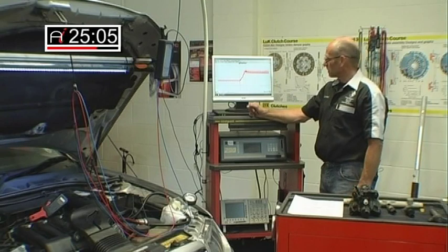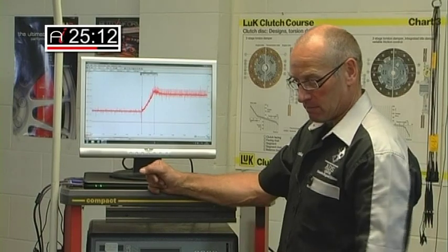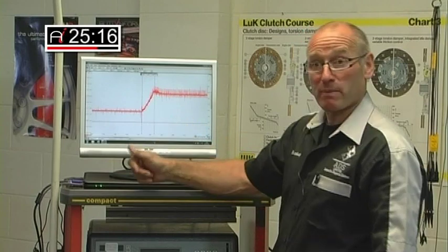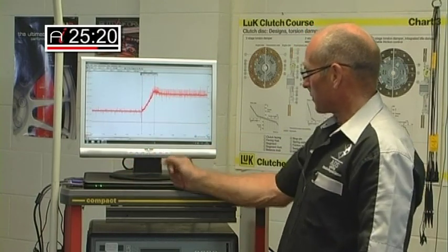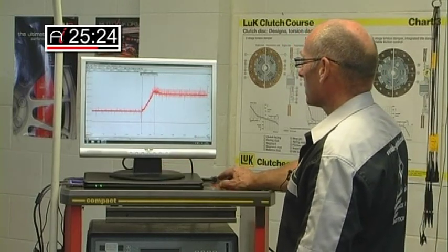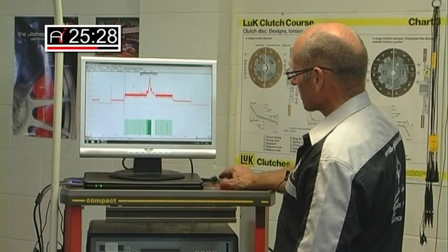That's excellent. There is nothing at all hydraulically wrong with this system. The priming system is working. The high pressure system is working. In fact, that wouldn't work if priming wasn't working. We know priming is working. We're monitoring that. There is nothing wrong with that. We now need to challenge this system on load, which is the acceleration test.